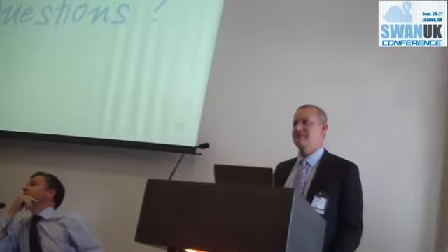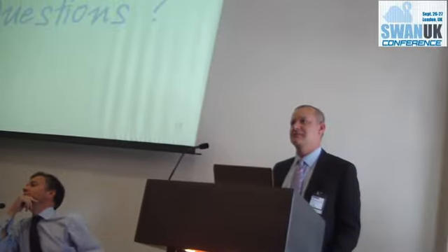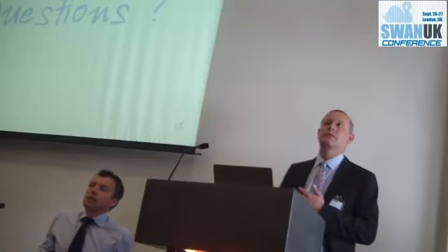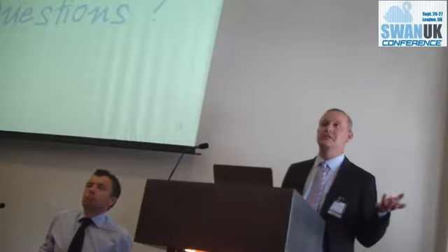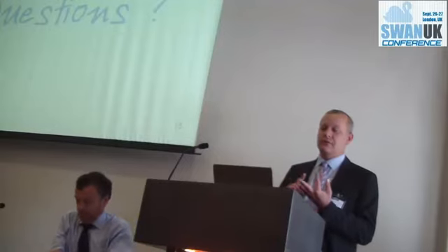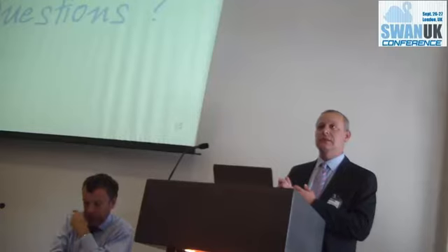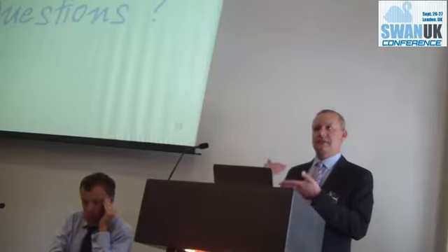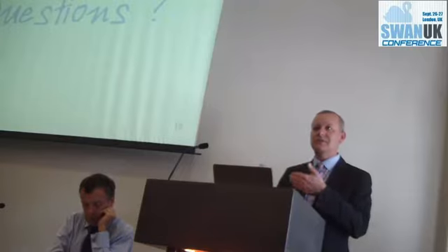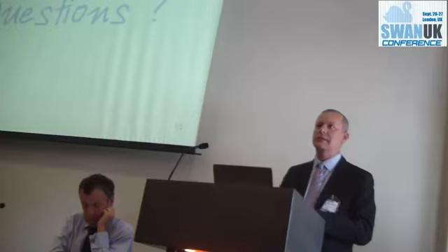Well, we'll take one more. Just one question. You're collecting quite a lot of data in the meter readings. Do you have any checks or verifications in place to ensure the quality? Yes, one of the examples is the meter accuracy, which will be checked at random on some meters, visually compared to what is being received. There are automatic checks from the Takadu software, where if there are any gaps in the data, or if a meter reading comes in and the next one is lower than the previous one, it is flagged. So we are going to do several automatic checks as well.